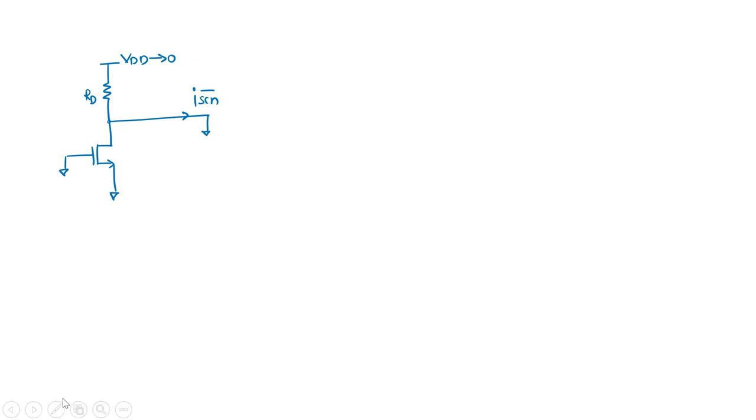Okay, so we can consider two noise sources here. One noise source for the transistor, that I'm representing using a star. If I want to give the direction, I'll give this direction, INM average. And the second current, I give this direction. Anyway, direction is not important for the noise. Once you have considered any direction, stick with that throughout your calculations. So this is your INR.